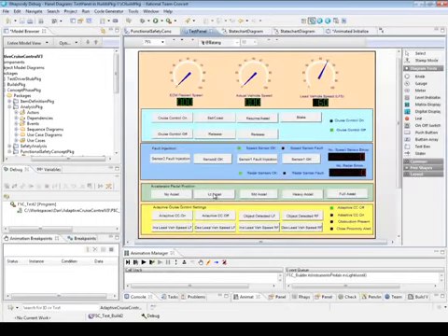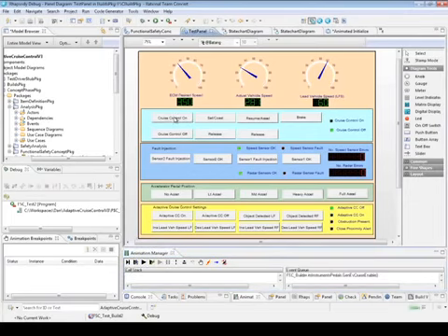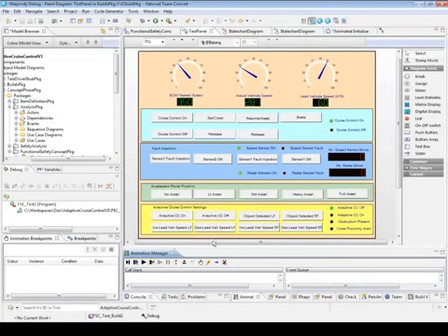So the first thing that we need to do is apply some pressure to the accelerator. I'm going to single step through the model. It gives us a lot more control. You can see the vehicle speed increasing in line with the desired speed as the pedal pressure is maintained. I'm now going to turn the cruise control on, and we can see that the cruise control is on from this panel, and we can also see it within the state machine. So that is now active.